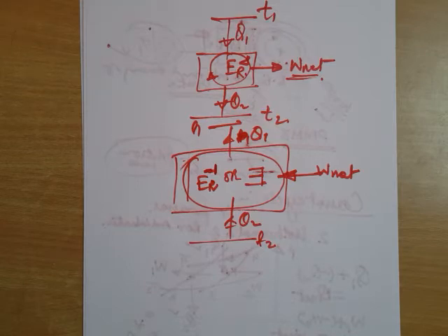So this is the thing which we have discussed. What we said is, what is a reversible cycle? A reversible cycle is that cycle which is performed in such a way that when the system is brought back to its initial state, the effect which the system has created in coming in the forward direction has been wiped out by the system in moving back.